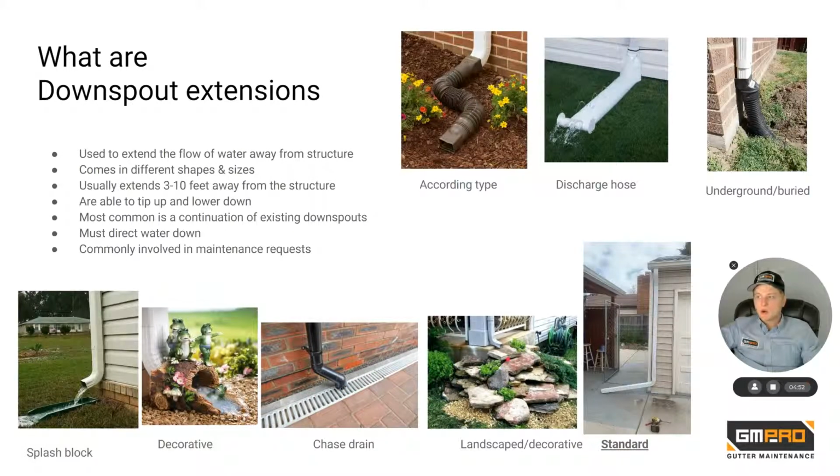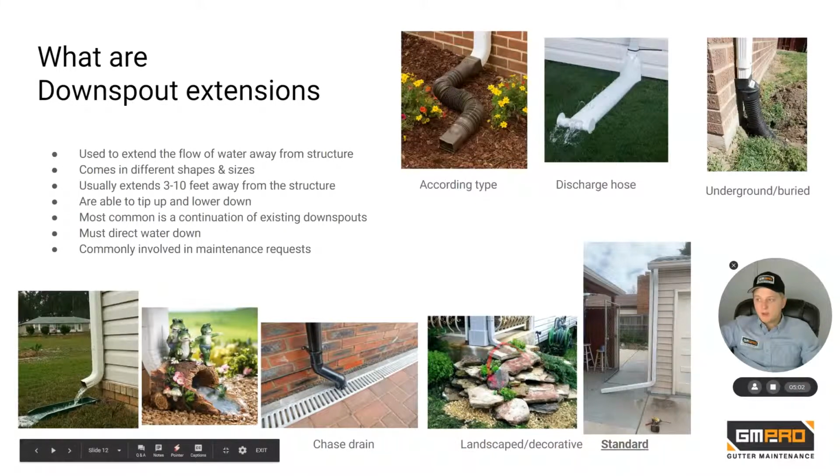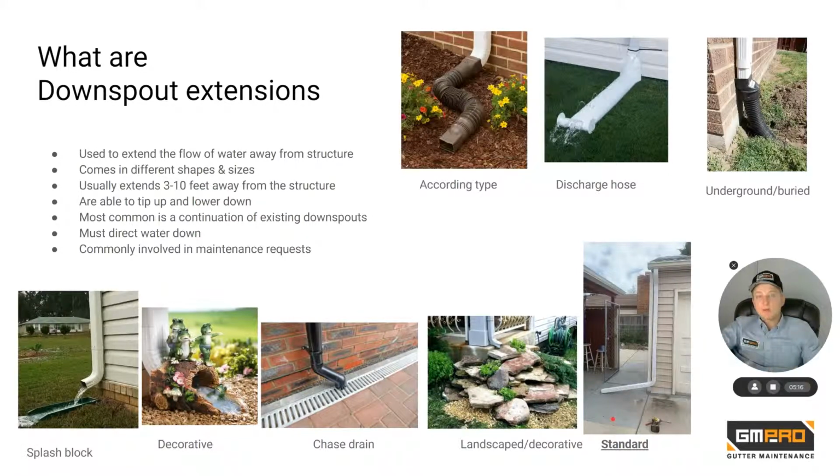You can also accomplish the same thing if you're trying to get water away from the foundation of the home by landscaping and being decorative with it. This is the most expensive option, but it looks really nice, and if it works for your home, that's great. This is just built out of rocks, and it's decorative, it looks great, but ultimately it's serving the purpose of getting water away from one place and directing it to another place.